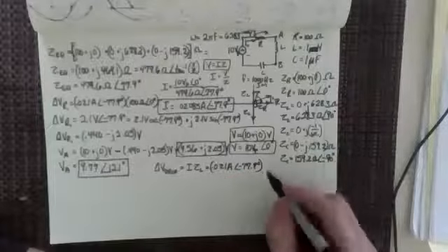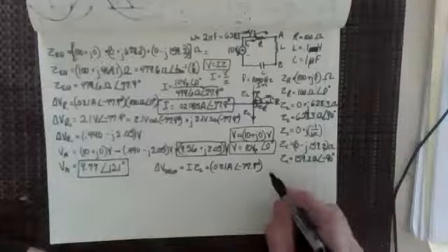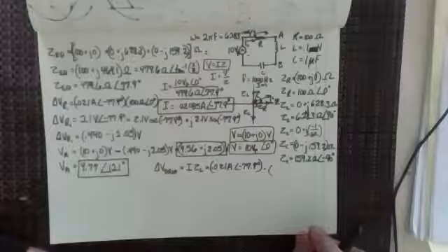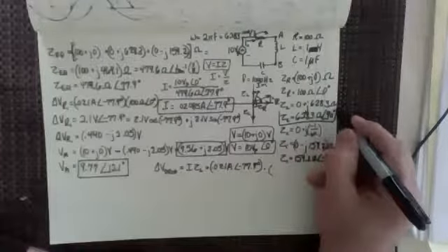And then we've got to multiply that, and I guess I'm going to have to go down a little bit because I've got that extra z sub c there, but let's just put a dot there so that you know in your notes that I'm actually multiplying it by z sub l. And if we go back to z sub l, there is my phasor notation for z sub l, 628.3 ohms at an angle of 90 degrees.